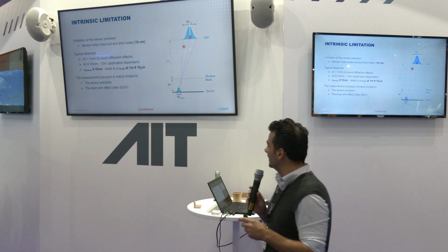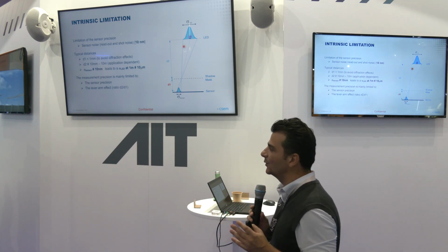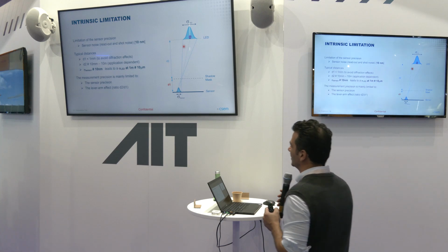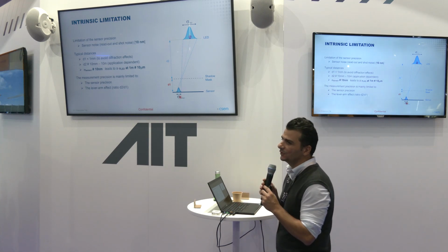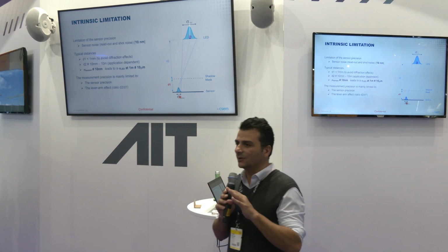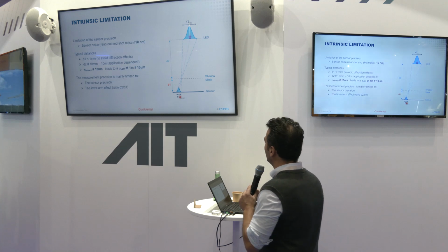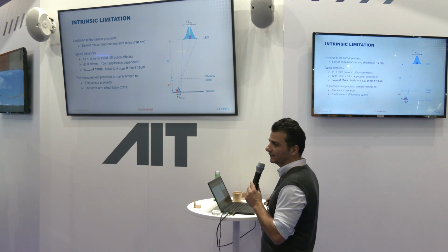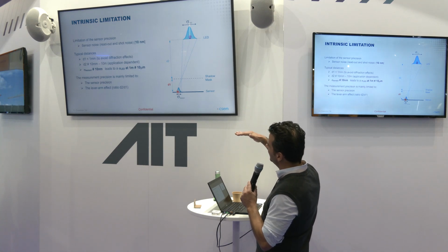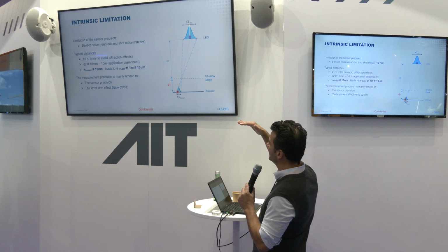Having said all of that, everything is nice and clear, but we have an intrinsic limitation inside the space coder technology, inside of shadow imaging. If I take the intrinsic limitation of a sensor, which is approximately 10 nanometers considering shot noise, electronic noise and so forth, and my shadow mask is located at a distance d1 from my sensor, I cannot glue my shadow mask directly on the sensor because then I don't have any shadow anymore, so I need a certain distance.